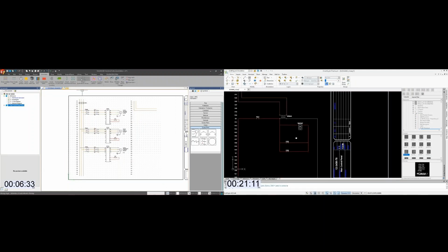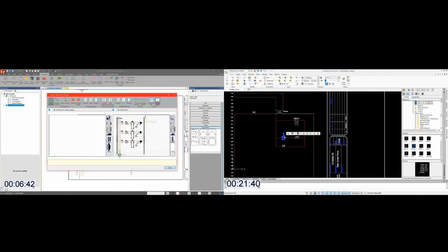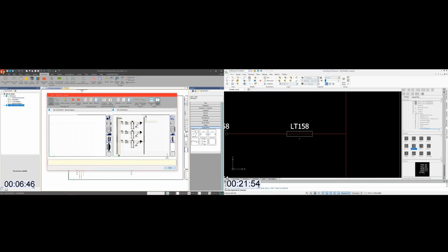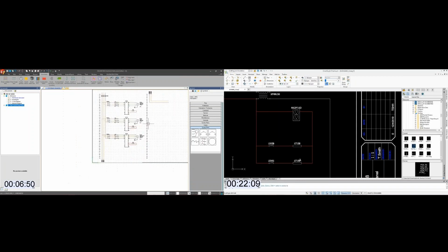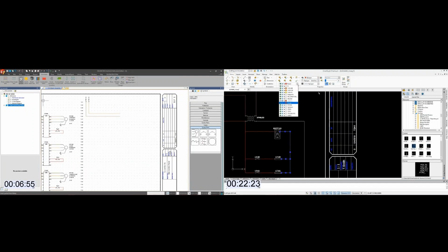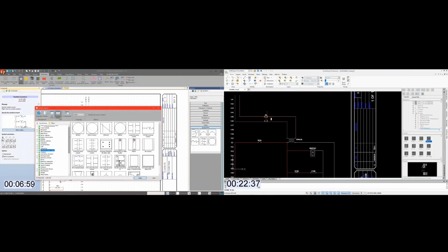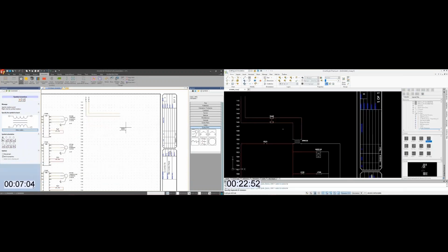All right, so checking in here again, let's stay in SOLIDWORKS Electrical, because here's a nice feature. What I'm doing is putting in intelligent source and destination arrows. So I'm saying this wire starts here and continues here, driving the intelligence of those wire numbers behind that. Once I make that association, all the wire information is intelligently fed through those connected wires through source and destination. Super easy to manage, compared to the manual effort on the CAD side, which can be complex.